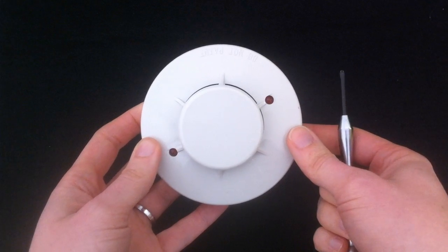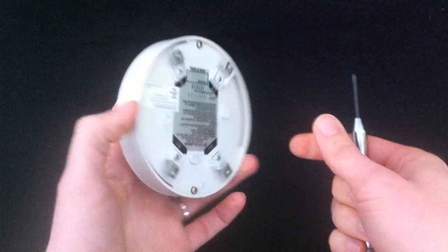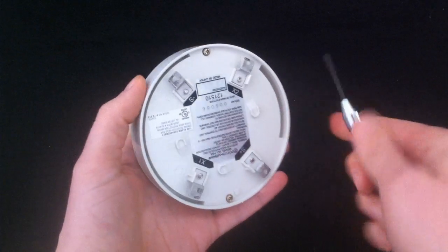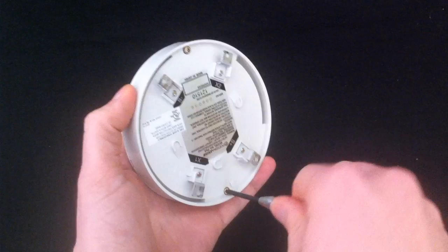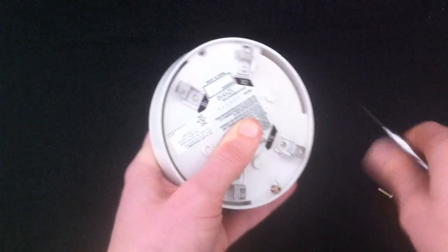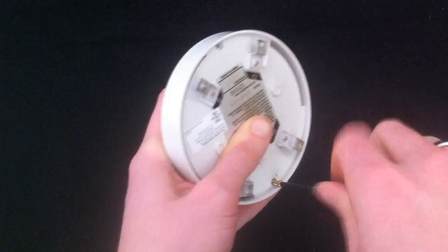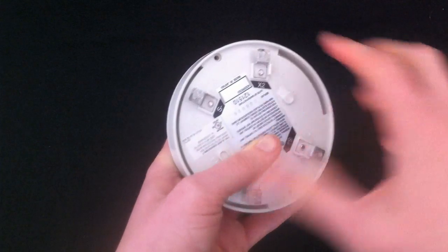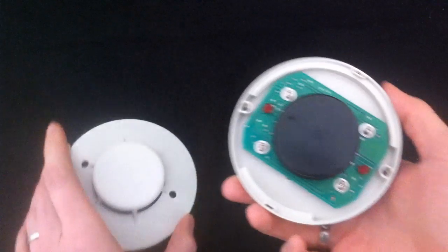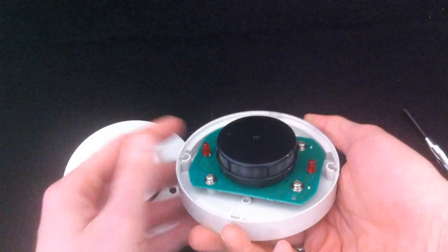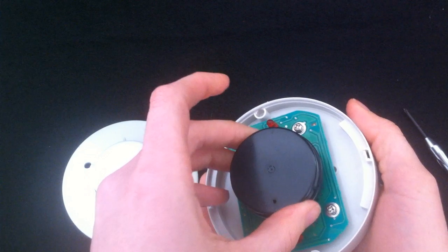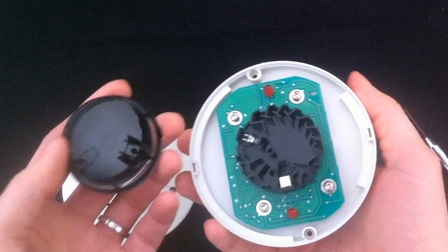As previously mentioned, this short video will demonstrate how to clean the PSA and the PSHA. When you turn the detector over, you'll find 2 screws. These 2 screws need to be removed to allow you to disassemble the detector. Once the screws are removed, you can remove the top cover of the detector. Once the cover is removed, you will see the photo chamber. The bug screen will need to be removed to access the chamber to clean it. The bug screen is clipped on, so you'll need to wiggle it just a little bit in order to remove it. Once the bug screen is removed, the chamber is revealed.